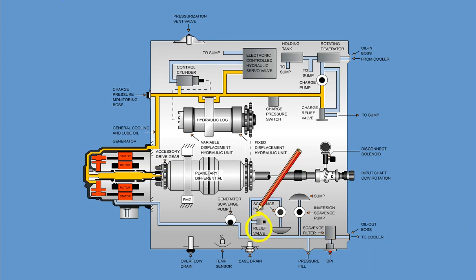The scavenge relief valve is provided for filter bypass and external circuit when the filter or external circuit remains plugged. In this case, the bypass oil flows directly from the scavenge pump to the deaerator inlet. The oil is still circulating within the IDG. Therefore, the moving mechanism still receives adequate lubrication. However, the oil is not cooled when the IDG is in the bypass mode.